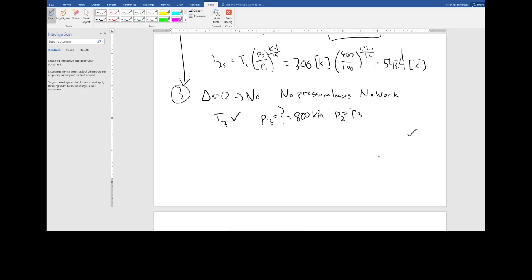So, you know, if you see a TS diagram for a particular cycle, maybe in a multiple choice question or something, maybe that gives you some information about what's going on with the temperatures and the pressures. Now, as I go from state 3 to state 4, this is my isentropic, or let's say ideal turbine.